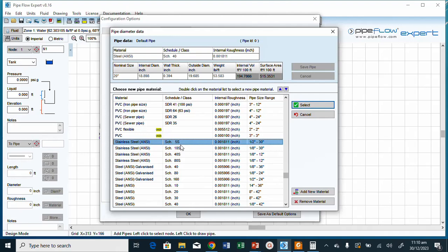So we are given, so what I will do now is, because we are going to also calculate using the general equation. I will put the proper pipe roughness they gave us, but the pipe roughness does not affect this equation because we have already calculated the pipe efficiency. We have inputted the pipe efficiency, which is 0.95.